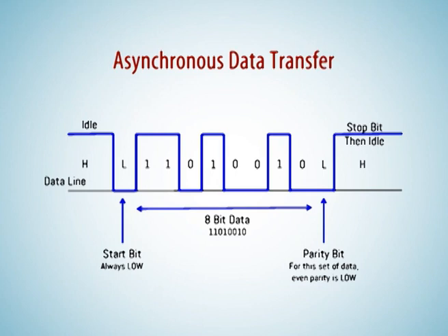So, to synchronize receiving of a group, the data stream is preceded by a start signal and followed by a stop signal. The start signal prepares the receiver clock for arrival of data, and the stop signal resets its state to enable triggering of a new sequence. Thus, the receiver clock synchronizes itself with the transmitter clock at the beginning of each transmission unit. The asynchronous method is very simple to implement in practical circuits. It saves one wire or link by not transmitting the sender's clock. In addition, it saves the complex synchronizing circuit and protocol deployed in SDLC and other methods.